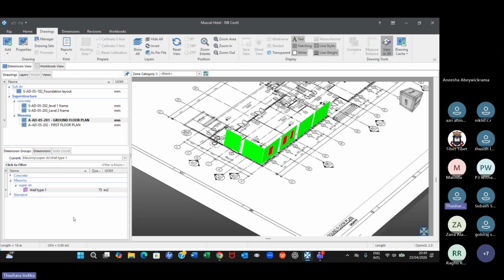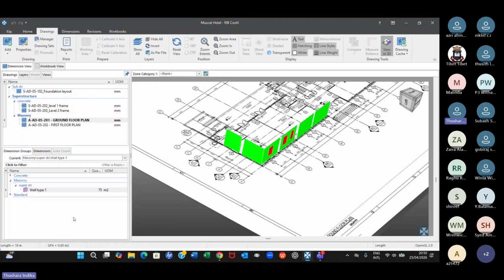Now, let us use windows today. Okay. And then how we can use another thickness or another type. Let's say now we have measured type 1. So let us measure another blockwork type and then apply these opening deductions, not as negative dimensions, but you can copy those windows into the blockwork dimensions group and do the deductions. Or we can use the workbook to deduct the window openings, either way. Right. So let's do that now.